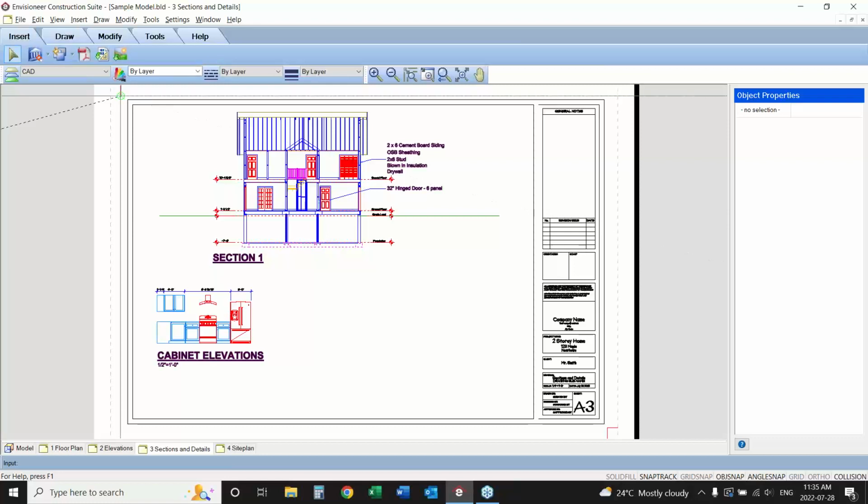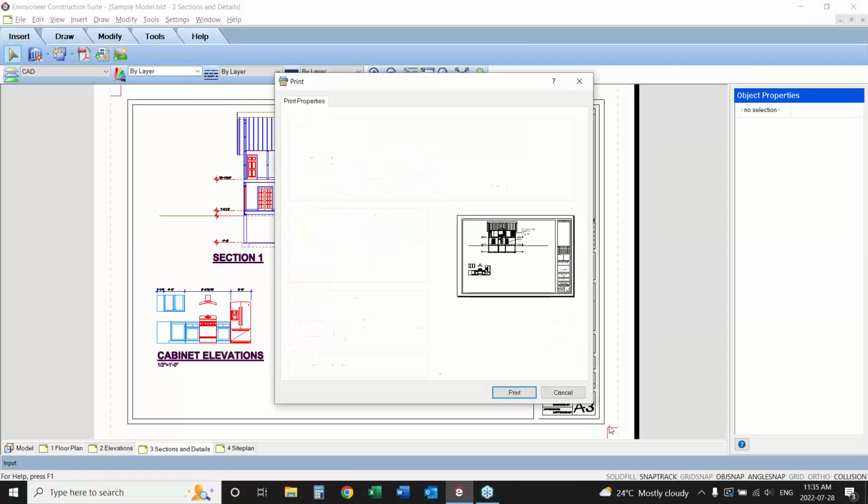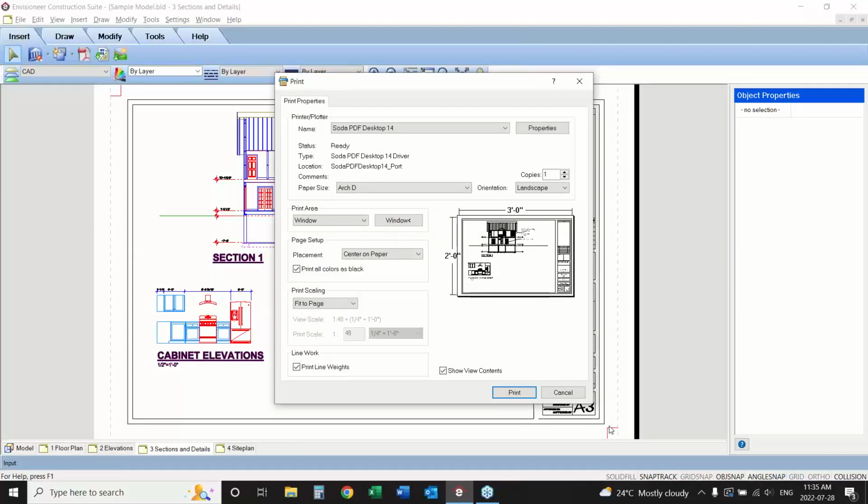By printing out to those points, it leaves blank paper around the black border line that it's going to draw. Okay, so instead of printing to here, which will eliminate that first line, print out to here so you can see those border lines. Left click there, bring your cursor down to the other corner, left click there. And that will leave an edge so you can see those border lines.